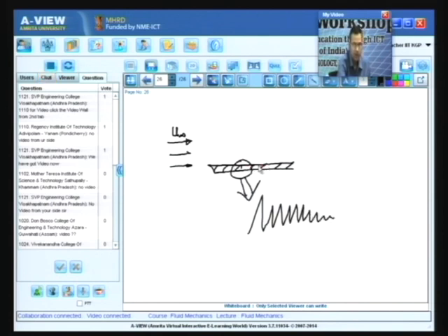The surface which appears to be flat macroscopically actually has a large number of ups and downs, and if we have fluid molecules, then these fluid molecules will remain in these asperities or in close contact with the solid boundary, and until and unless the shear force is abnormally large, it is very difficult to dislodge them from the contact with the solid.